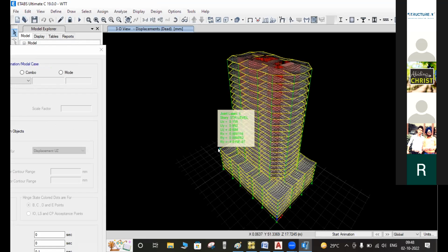Is there any kind of provision to check that minimum deflection? Basically, when we study the IS standards, for the deflection, I think it is the span by 250, the formula will be that. So identify that deflection also. The gravity deflection we control by modifying the slab and modifying the nearby members.